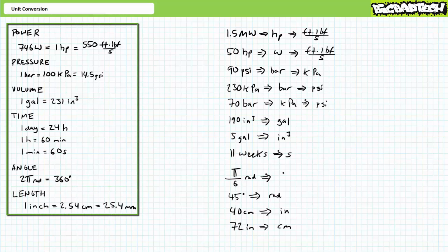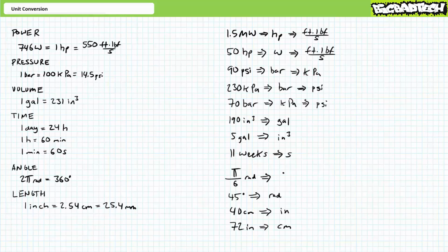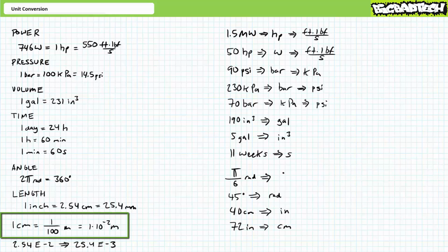It might be worth a moment of your time to copy these conversions down on your cheat sheet because one day this material may or may not show up on a quiz. Hint, hint. A brief explanation about centimeters. Despite their popularity, centimeters aren't really official engineering units. 1 centimeter is 1/100th of a meter, or 1 times 10 to the negative 2 meters. If we use proper engineering format, 2.54 centimeters would be expressed as 25.4 millimeters, which is a proper engineering prefix. So you can add this additional quantity to our equivalencies, such that 1 inch equals 2.54 centimeters, which happens to equal 25.4 millimeters.